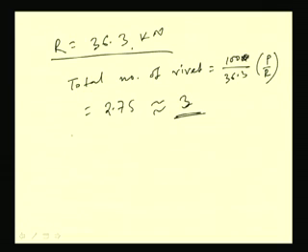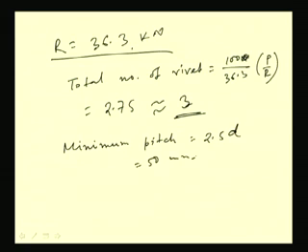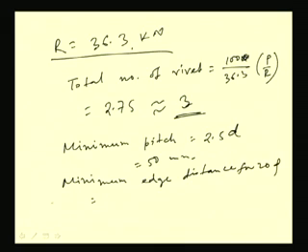Now, minimum pitch is, generally we used to make at least 2.5 d, that means 50 mm, right, and minimum edge distance as per the codal provision, this will become, for 25 rivet diameter, minimum edge distance will become 29 mm.